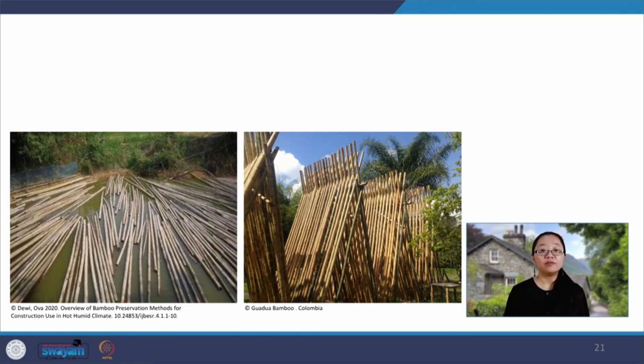Different cultures have different ideal times to cut bamboo, usually connected to the moon cycle. There are many ways and vernacular techniques for bamboo treatment before construction. In Southeast Asia, the most common technique is to soak bamboo in running water such as a river, or to soak bamboo in salt water for at least 7 days, depending on the species and age of the bamboo. Then air dry the bamboo with natural ventilation and sun.